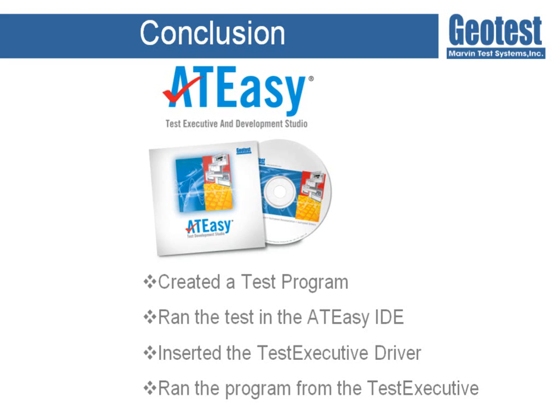So this concludes the introductory ATEasy video, where I created a test program which used a power supply, a matrix, and a GPIB DMM to take a few readings and do some pass-fail analysis on them. I ran the test in ATEasy within the integrated test development environment, and then I linked in the Test Executive so I could easily bring in the built-in graphical user interface to my project.